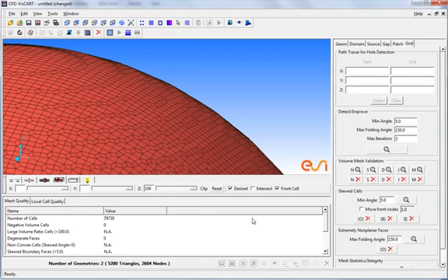In single-domain meshing, the projection of cells to capture the geometry curvatures results in the creation of non-Cartesian cells. To ensure that these cells are of good quality, the mesh should be improved using the Mesh Quality Detection and Improvement tool in the Grid tab. Note that the Explorer displays not only the cell count but also a number of mesh quality statistics pertaining to the generated mesh.